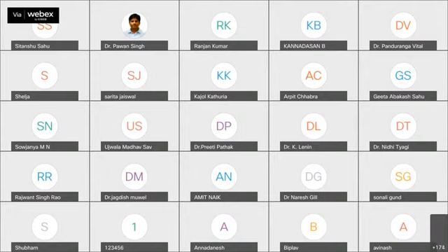And if you look at the green one, the IMF5, it captures the fundamental frequency. The peak shows around 100 Hertz. So that means the variation in the frequency, of the vocal fold as well as the vocal tract, both frequency information is captured in different IMFs. Then the energy content in these different IMFs will give us an indication whether the speech signal is of Parkinson type or healthy type, right?